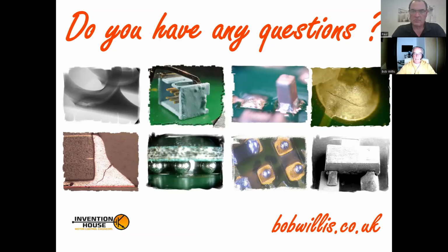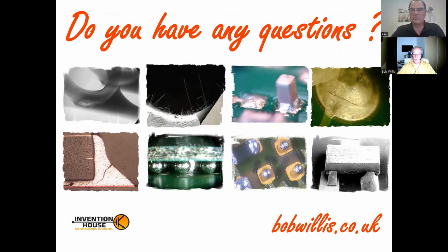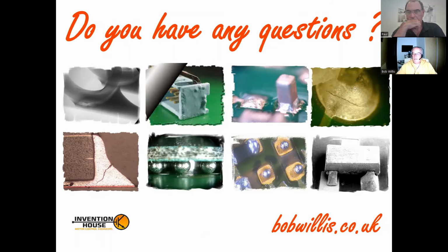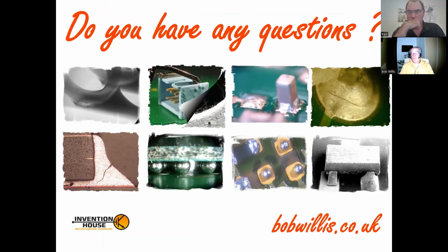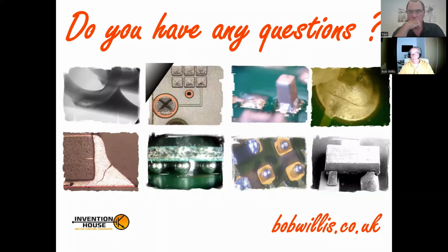If the tin plating process, the material that's used, the plating that's used is poor, incorrect, you can get whiskers. Doesn't matter if it's an inch apart, 1/1000th of an inch, or a couple of microns apart, you could get a whisker. So if the process and materials are in place correctly, which generally speaking they are today, we don't see whiskers like we used to. It shouldn't be an issue.